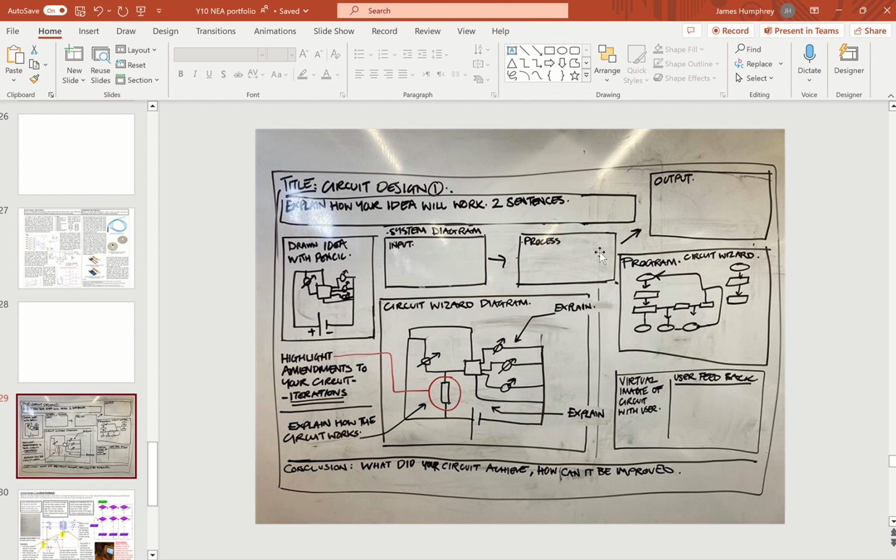And then in the process of it, when D2 on the Genie goes high, my Genie will produce a random number between 1 and 85, and that random number will be displayed on two 7-segment displays, because the output of my Genie on Q1 will pulse that number of times. For example, if the number is 72, the leg will pulse 72 times. Then the output might be an LED, or for example, a 7-segment display.